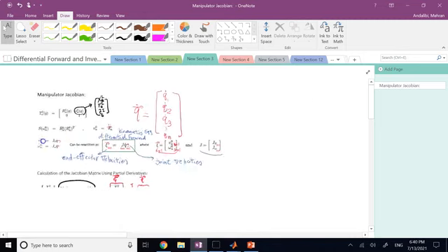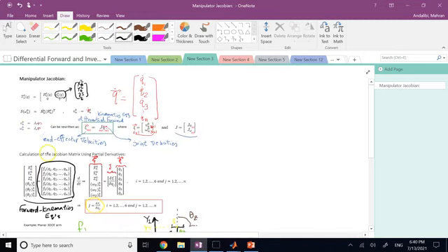So these three things that you wanted, the first three functions, they come directly from the elements 1 and 4, 2 and 4, and 3 and 4 of the homogeneous matrix of the end effector.